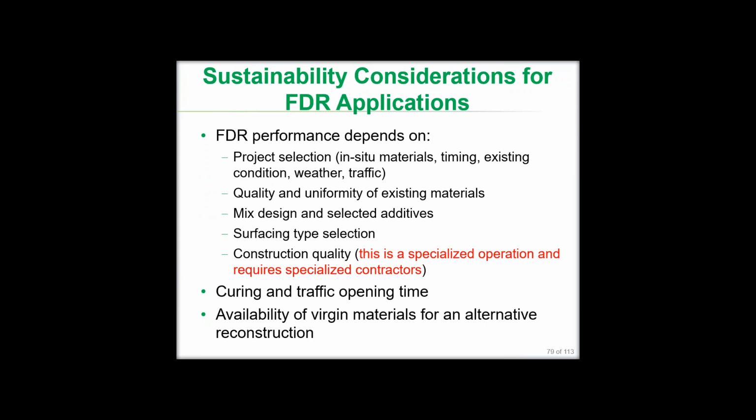And some of the final sustainability considerations for FDR applications: of course, performance is the most important. And how do we achieve performance? With some of the items that we just discussed in the previous slide: the project selection, quality and uniformity of existing materials, mix design and selected additives, surfacing type selection for the existing conditions and requirements, and finally construction quality. Since this is a specialized operation and requires specialized contractors, construction quality becomes an important consideration for achieving the desired performance. Some other sustainability considerations for FDR, and generally for other in-place recycling techniques, are the curing and, of course, the traffic opening time.